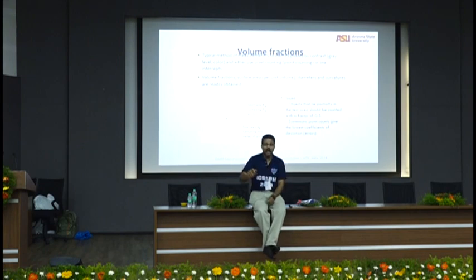So you go one step, and on my left hand, this is like a very sensitive operator here, I have a counter with 3 buttons. On my right hand I am moving in the X and Y direction, and I am looking into the microscope. I turn one step. If the crosshairs fall on a pore, I press the pore button. It counts the pore. If the crosshairs fall on the paste, I press the paste button. If the crosshairs fall on the aggregate, I press the aggregate button.